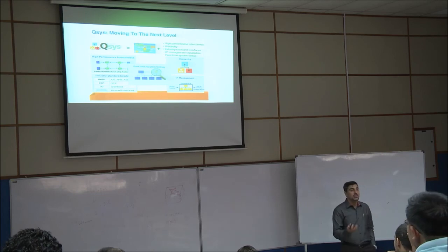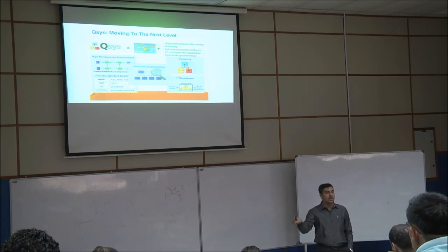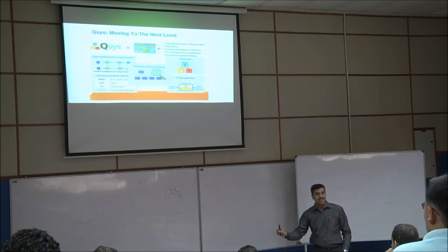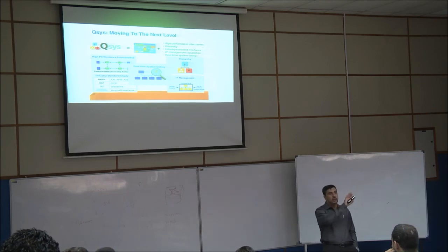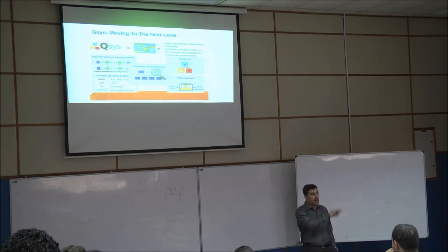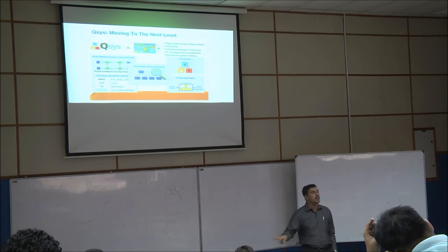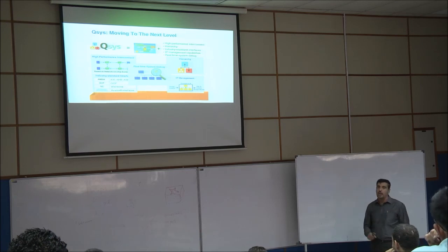So to do SoC design, we have to use Qsys. Qsys means the system we can build inside the FPGA by using the Qsys tool. Actually, we call it System on Programmable Chip. The early version was called SOPC. Now we're using Qsys. When using Qsys, we utilize modules, megacores or hard cores, soft cores, sorry, and put them in the map. Then we ask Quartus, the CAD tool, to generate the netlist for us. Then we can use it on the FPGA chip. Clear? So Qsys is one of the very important tools inside FPGA technology.